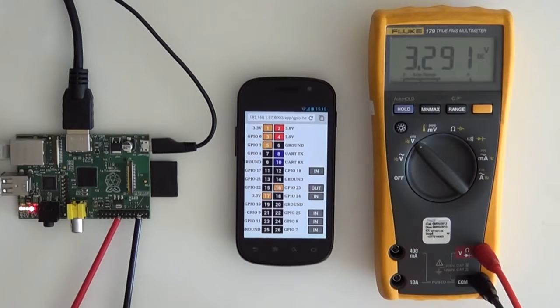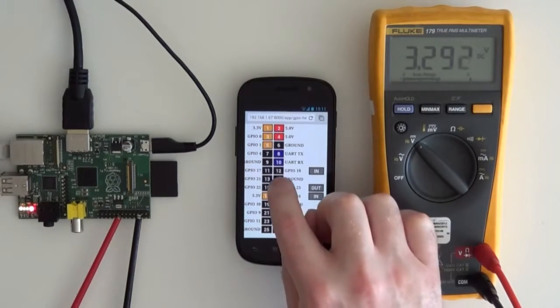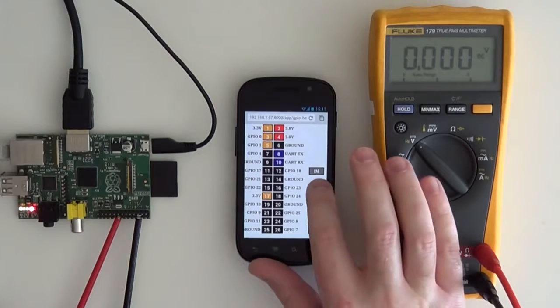I haven't got anything to put on the end of the pin, so we'll just connect a multimeter so you can see the voltage output. The ground or common output pin will always be the same, it's pin 6. I've connected the negative meter lead to that, then the positive one to the pin we're testing. Then I can press the button on the web page to turn the output on and off again. It's that simple.